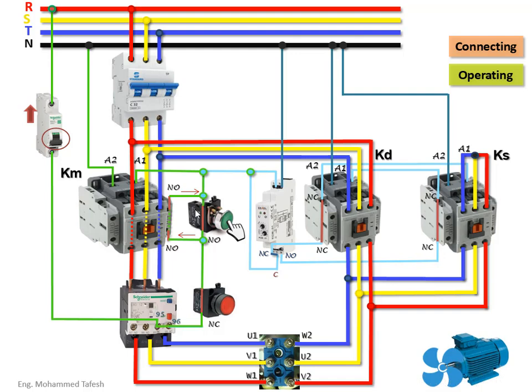Thus, the electricity entered completely and returned to the coil, which led to turning on the contactor Km and completing the circuit, and the electric current passes through the timer. We took it from point 12, which is a common point, and the current will continue to pass in the closed path, as you see here.